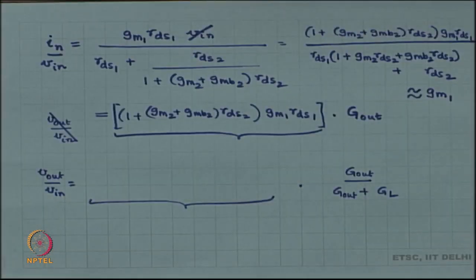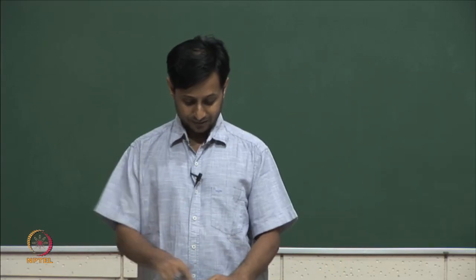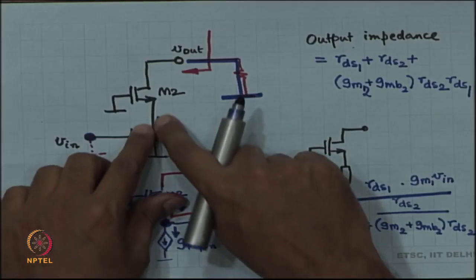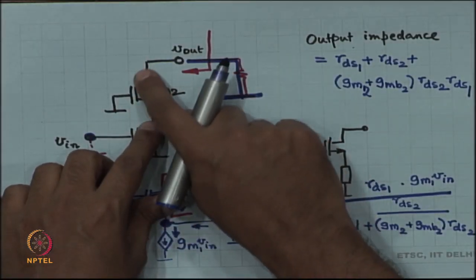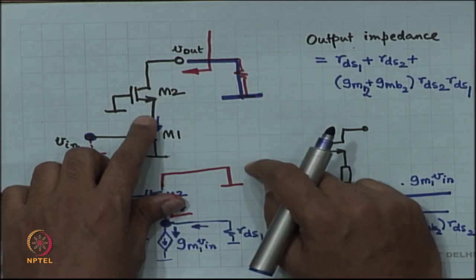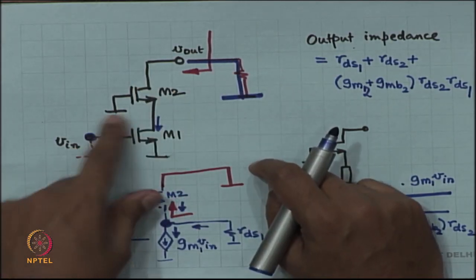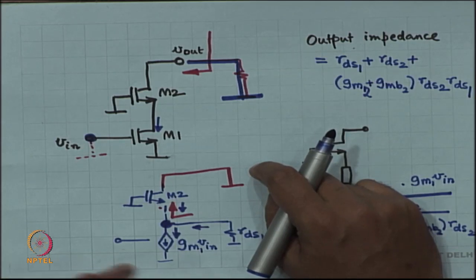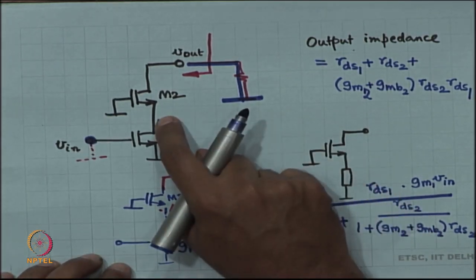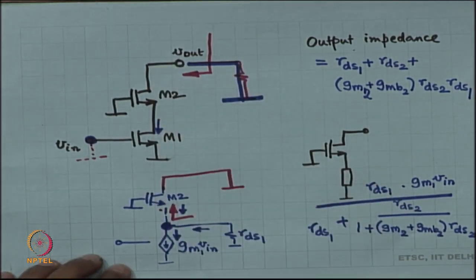All right. So, this is something very important that happened. You almost sent all of the current. So, this is a current controlled, this is what happened over here. M2 is a current controlled current source. Remember, this is a common gate structure. So, whatever current went inside, it came outside, right.